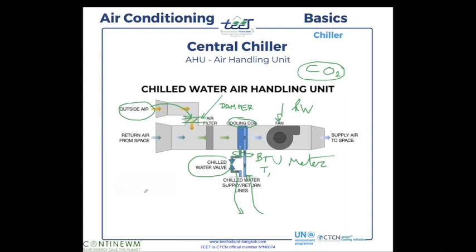So with that said, I think our energy validation in terms of savings would not be as much as 20%, maybe slightly less, right? Yeah, the quantity of outside air in general is 5 to 20% of the total amount of air that goes into the building. Okay. All right. Got it.